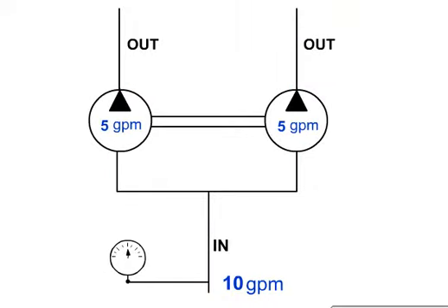Gear-type flow dividers can be used to combine return flow in circuits. Most spool flow dividers are not designed to allow reverse flow through them. There are spool-type combiners and combination divider-combiner units.